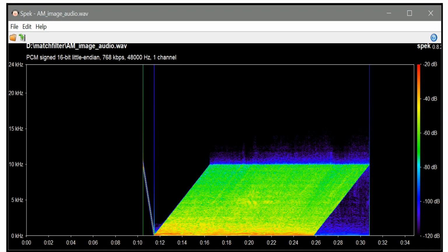And then all this blob here is the image converted to a one-dimensional vector, and then we've convolved the chirp with the opposite slope across all those pixels, and that's what you're seeing here. So on receive, I first find this chirp that tells me the start of the file, and then run a matched filter against all this data to compress and get that final image.